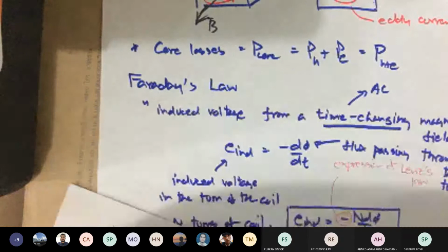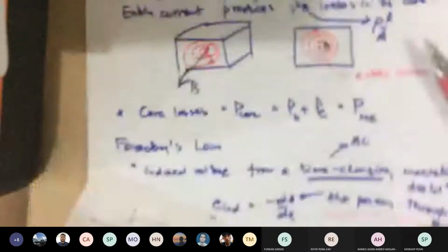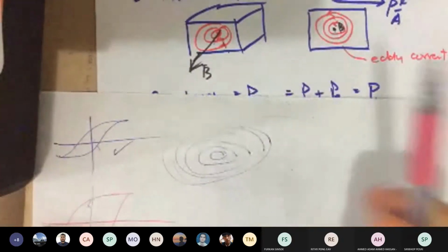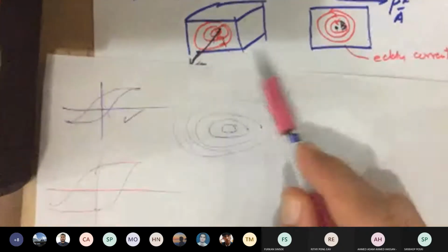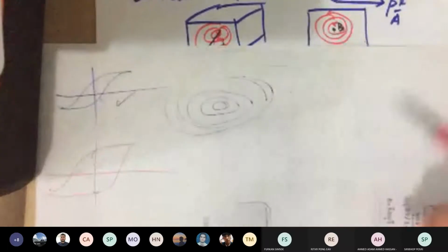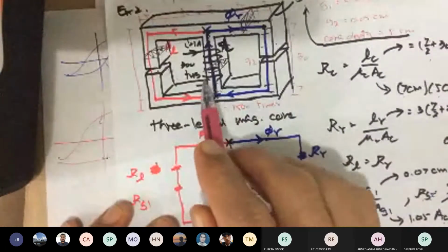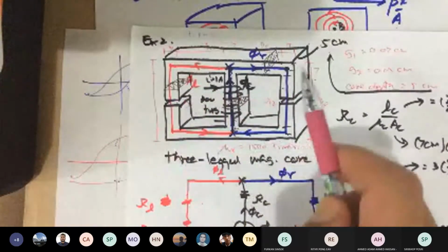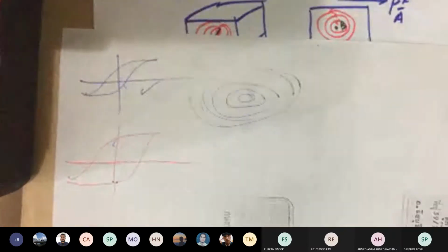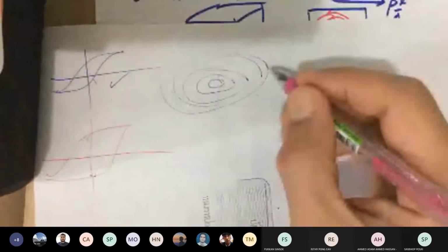Now back to eddy current a little bit. If you notice your electrical machine inside, not the casing, the one that you see in the lab is the casing of the machine. The one that has windings contained, like the transformer, everything like that. Your core, like the one in your example, if it's a properly designed core, will never be made of solid iron, a chunk of iron. Meaning, if I have a core, let's use a simple one, the square donut core.